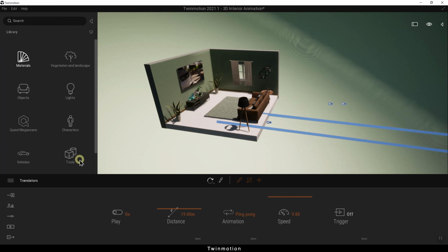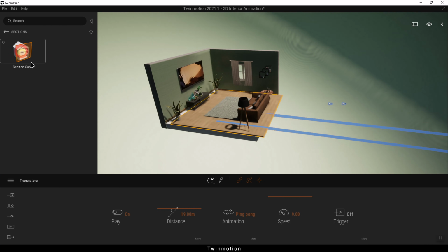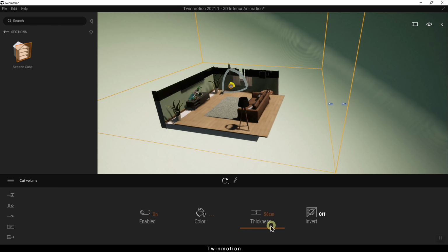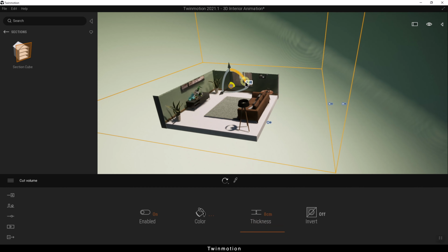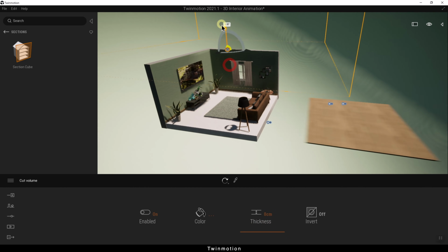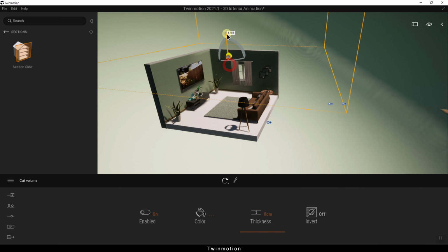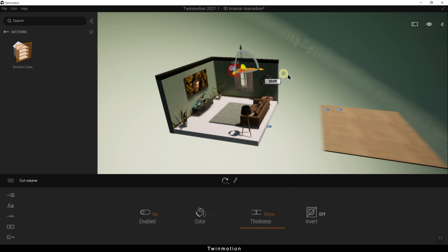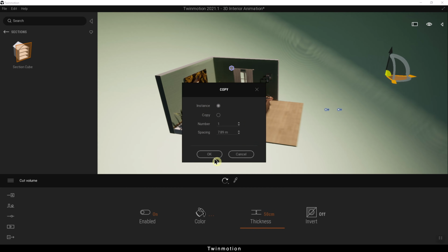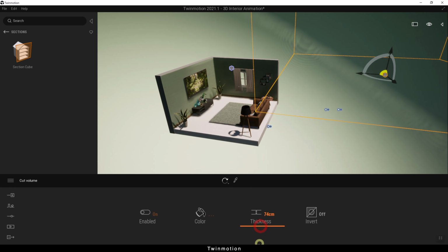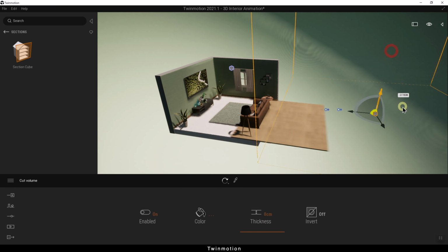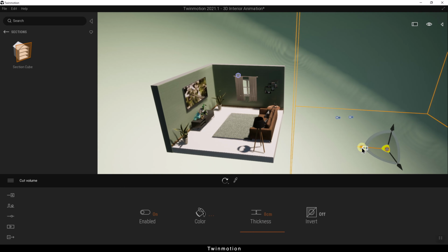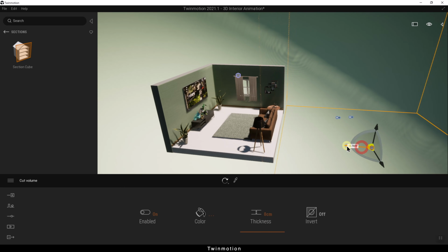But a very important point, we enter the tool section cube, I put it here. We raise it a little higher. Here we set the thickness to 0. We bring it up to exactly this edge. Objects that come from above appear suddenly. Hold the shift, move it forward, click copy. Set thickness number to 0 and move it down.